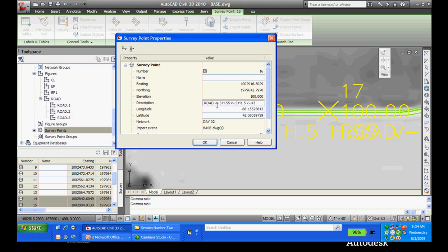It should have been a negative 0.5 offset for the other side, and then this one would have been negative, and then this would have been negative as well. The verticals were fine, they just offset them to the right. They should have been offset to the left. All right? In our last version of the software, you would have been back tweaking the original field data out there and then reprocessing it again. Here I can change it within the file.